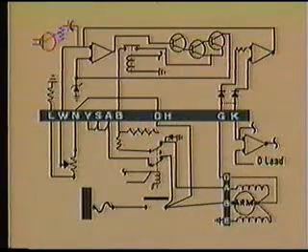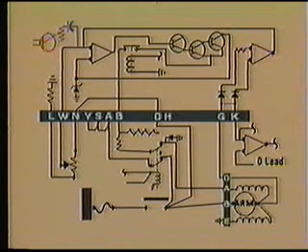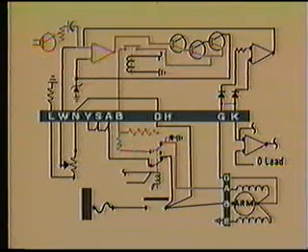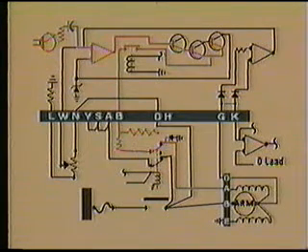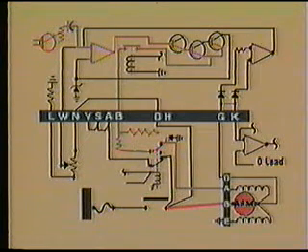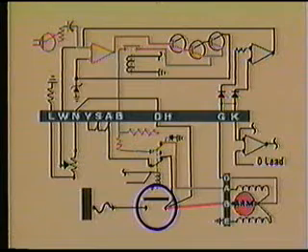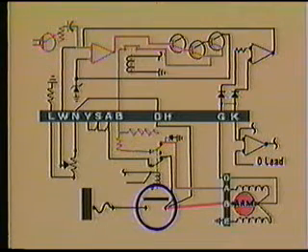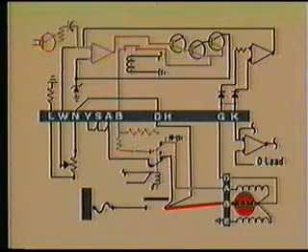Now let's consider some operational conditions and how they affect the regulation circuit. As soon as power is provided to the control panel, the oscillator circuit provides an output. This output is duplicated in the output of the operational amplifier and through the circuitry that boosts the signal level provided to the A-lead. Since we are now exciting the field, the output of the generator will begin to increase. Note that this increase in voltage produced is occurring without the main contactor being closed, nor the generator on the line. As the generator voltage increases, the voltage at the B lead will increase as well.